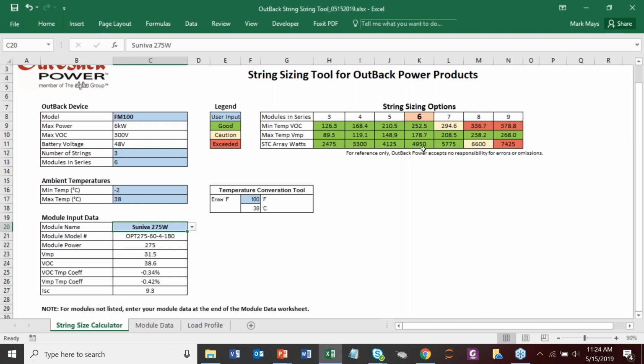So that doesn't really give us any advantage, other than maybe if somebody's having a fire sale on some 275s. You still may want to consider going 6 in series. That's going to give you 4,950 instead of 5,400 watts. Anyway, these are some of the what-if scenarios that you can go through with different modules.